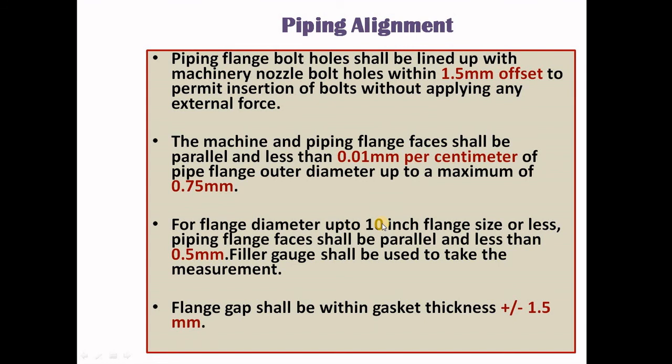Piping alignment, I have told you: if the piping has stress, then this will create a soft foot, and if you compensate this pipe stress with alignment readings, your purpose will not be solved. Your pump will vibrate when it is running. So the stress should be eliminated.